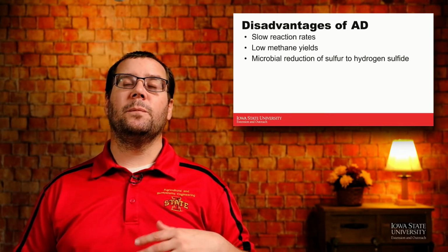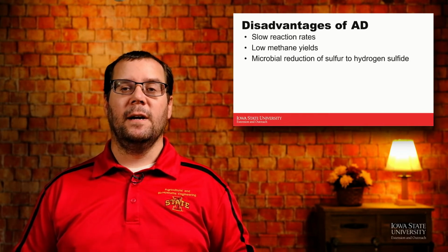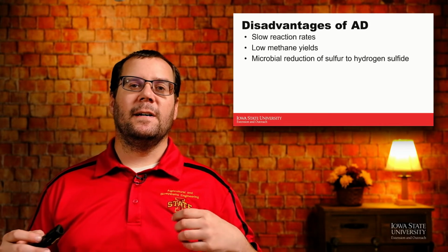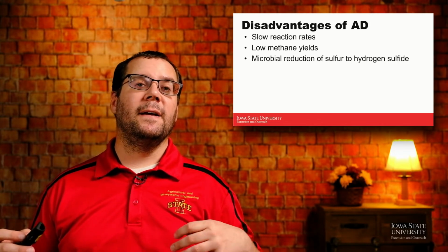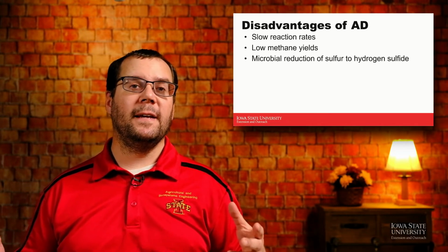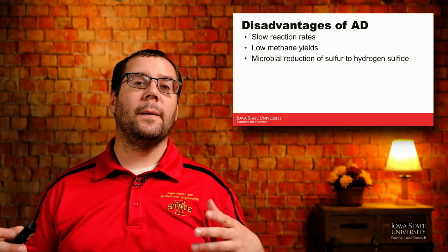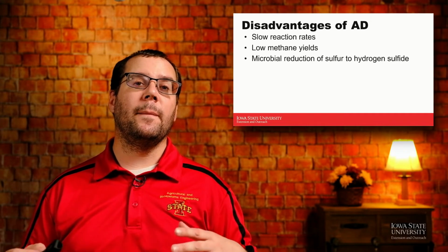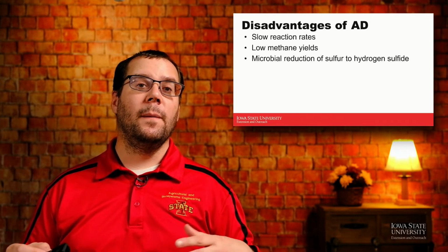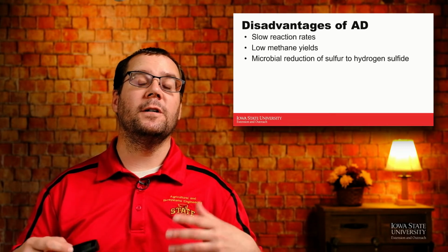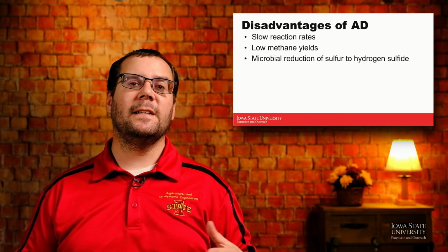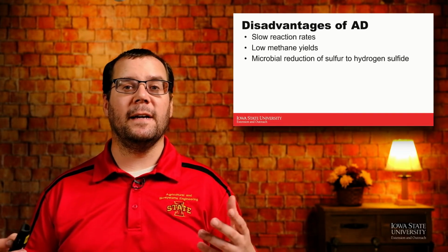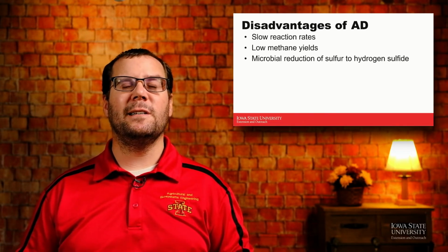Another disadvantage can be relatively low methane yields. And low is sort of a relative word, right? Because we can have different reactors that can make what I would say higher amounts of methane, but still when you compare them per cubic foot of reactor volume and compare it to something like ethanol, we're making a lot less methane energy per reaction vessel volume per day. That isn't necessarily an insurmountable challenge. It's just something that, again, ends up with bigger tanks and some bigger initial costs as we size that facility.